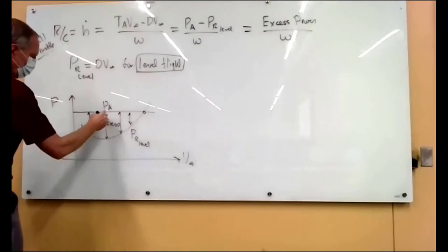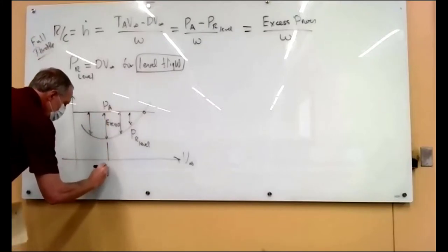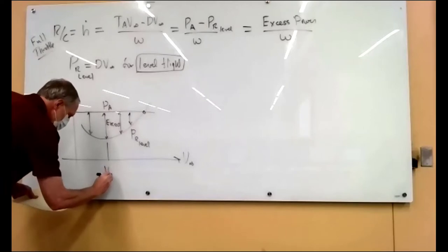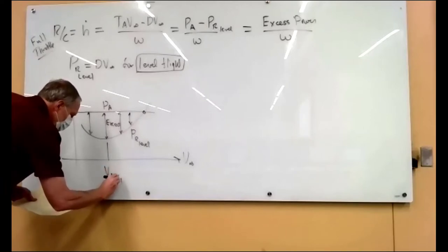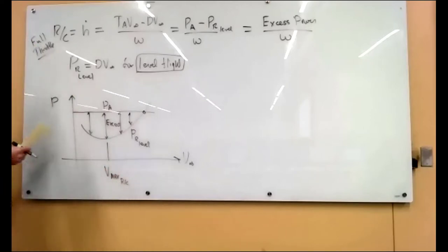And so you can see that there's going to be a spot here for maximum rate of climb, or what you would more commonly refer to as best rate of climb. So if you wanted to get to the altitude the fastest, you would fly at that airspeed because it means you have the most excess power.